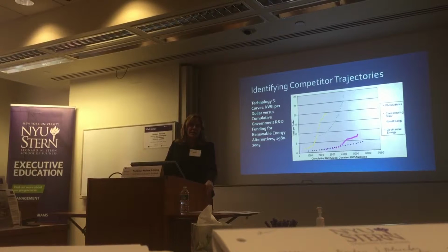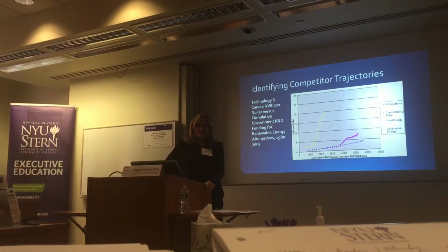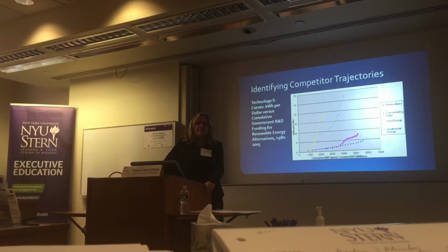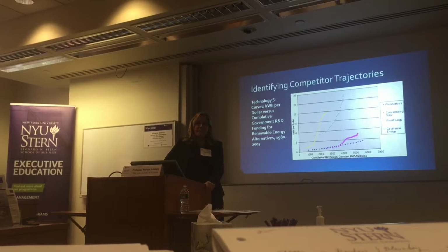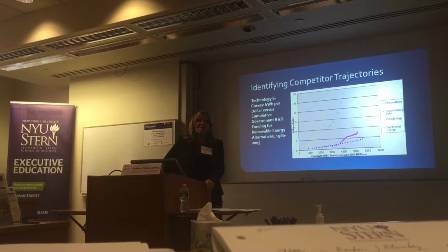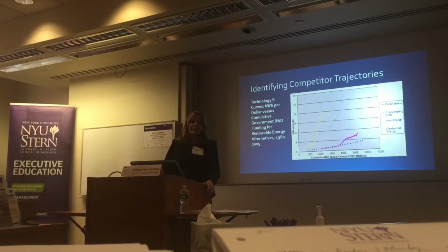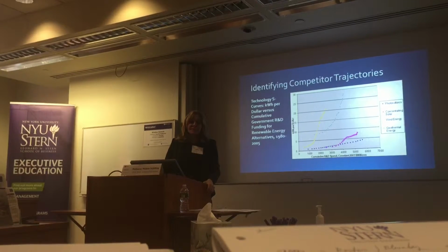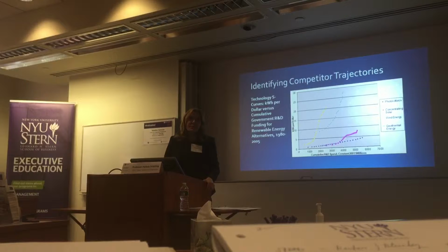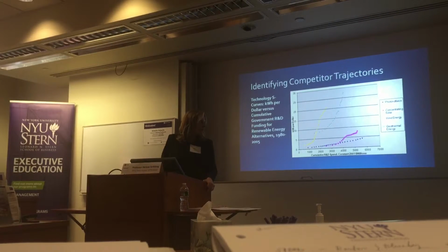Yeah, so the big part of photovoltaic failure is dielectric failure, which is essentially the business of DuPont making an encapsulation material that prevents that kind of thing. It's an expensive bill of material in addition to the silicon. It's up there with the silicon class. They may not be using a reliable encapsulation material and saving money that way.